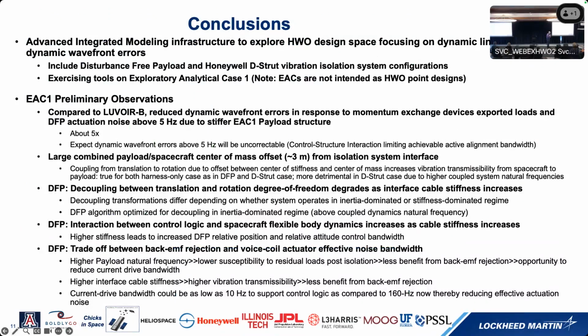So there's a number of observations and lessons learned on this. One is the natural frequency of the payload in the system at 10 hertz is significantly higher than what we have worked with in the prior iterations of HWO25, for example, when the natural frequency was 1.5 hertz. Keep that. It's really important.